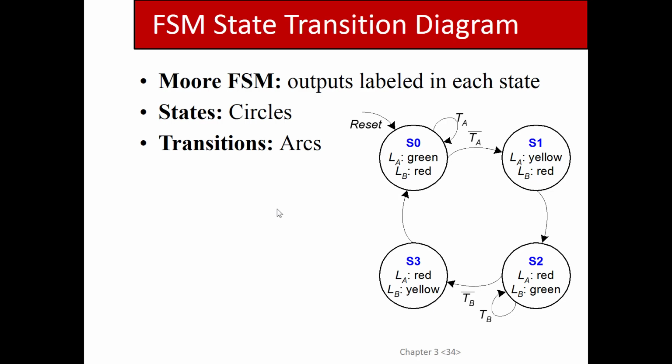And so whenever we go from green to red, we go through this transitionary state for one cycle. In this case, one cycle, the period of the clock, is assumed to be the length of time that the light is yellow, right? So obviously, if we were running this at 200 megahertz or gigahertz, this wouldn't make sense, because as we pass through this yellow light state, it would only be in there for one cycle, and you wouldn't see it actually turn yellow because it would be too fast. You guys with me on that? Does that make sense? Okay.